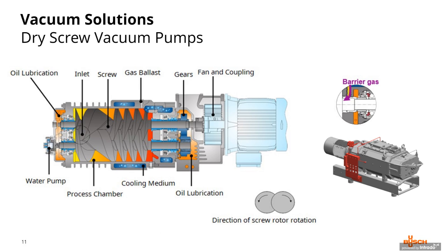The dry screw is a single-stage twin screw vacuum pump. The cooling jacket ensures even temperature distribution and greater thermal efficiency and stability throughout the pump body. The modern screw pumps have variable pitch screws, which result in even compression of the gas across the entire length of the screw. There are many advantages here, from ensuring even temperature distribution that can be easily monitored and controlled, to low power consumption from energy and cooling water savings, as well as low gas temperature. There's no compression against the end plate, eliminating the possibility of hot spots.